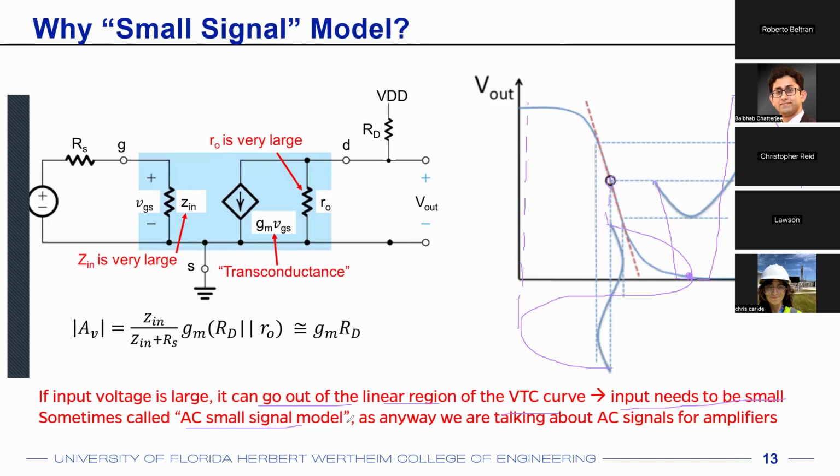Exactly. Because I skipped a few slides, don't look at this right now; I'll be explaining that. But again, you know the Thevenin and Norton equivalence. It's basically your homework problem 4 and homework problem 5. They are talking about the same thing. You can represent this dependent source either as a voltage source or a current source. Two slides back, it was shown as a voltage source. That was the Thevenin equivalent. Here it is being shown as a current source, which is the Norton equivalent of the same thing.